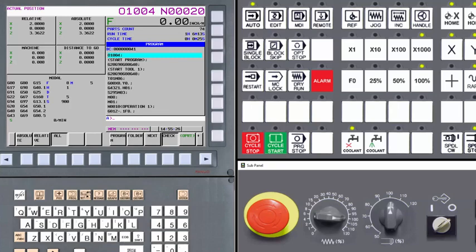The rapid positioning move can also be very intimidating for an operator verifying a new program. Therefore, there's usually some way to independently slow down rapid moves. It may be a selector switch similar to the feed rate override. In this case, we have 4 switches setting the rapid rate to 0, 25%, 50%, or 100% of the machine's normal rapid rate.